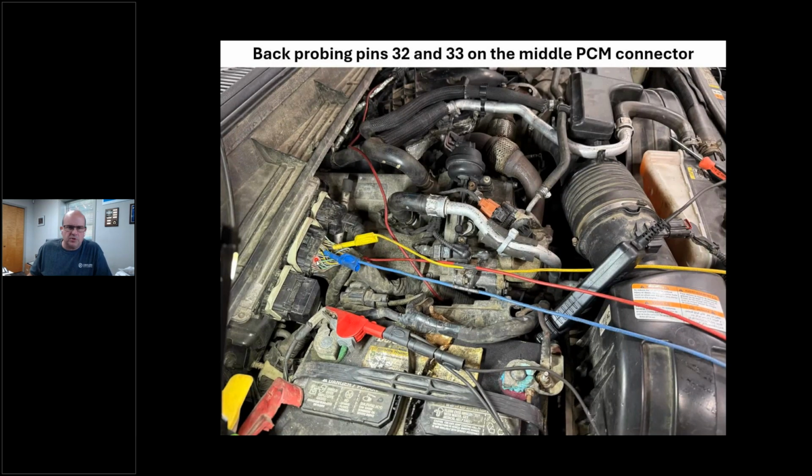And I take a little small screwdriver. We're not hacking the customer's car up, or truck, and we're just going to peel back these little tabs here, and I'm going to cut the tape at the bottom because there's a little bit of tape wrap on that, okay? And we're going to pop this guy off, and I'm going to back probe those two wires, okay? Not that hard. It might take you 5 minutes to do this. One nice thing about these Fords, I can get right up here next to this battery, and this connector stares me in the face. I'm not in a lot of messing around. I can get right in here, and this is where I'm going to get this information on this truck.